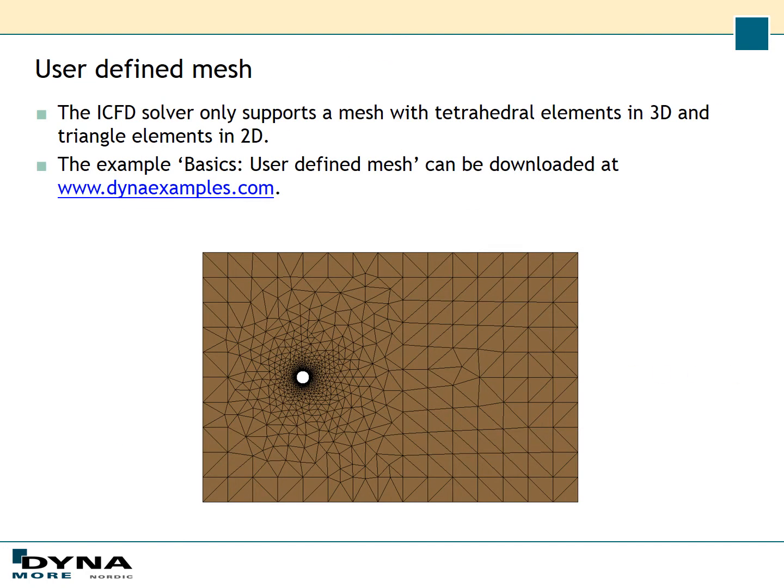If you instead use a user-defined mesh, the ICFD solver only supports tetrahedral elements in 3D and triangle elements in 2D. You can download a basic example from dynaexamples.com that shows how to set up a user-defined mesh. I will go through a little bit of the steps that you have to take to use a user-defined mesh.